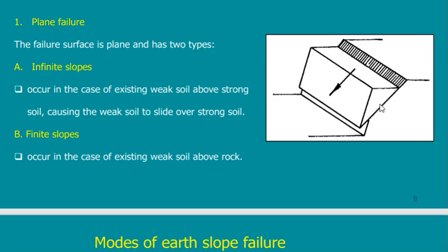If I calculate the shear strength of this line, it means that the load of this wedge was more than the shear strength of the soil at this line. So failure happens. So it means that you have first to assume the shape of failure, then to calculate the forces and to check this case. But maybe this was not the failure case. Maybe the failure case is bigger. I mean that imagine that you have a line here like this, a line parallel to this line, but it is a little bit below.